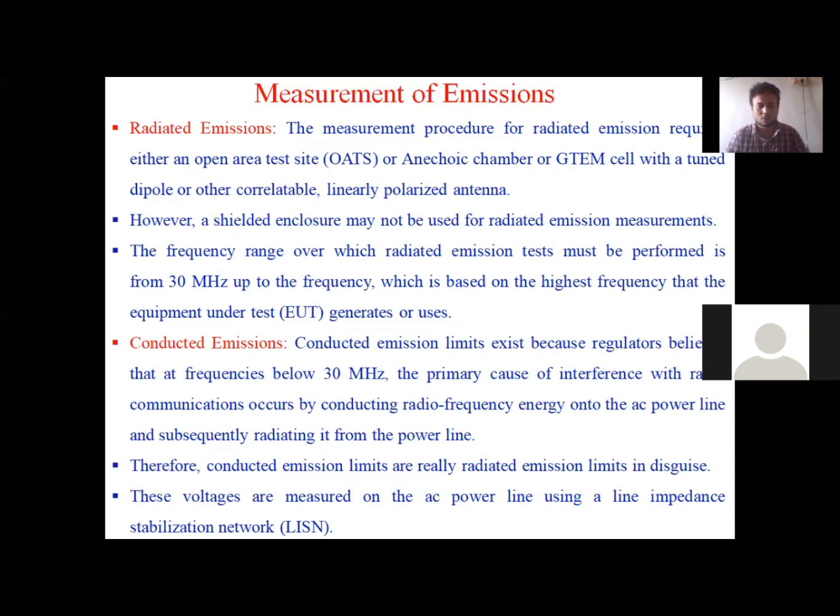Anechoic chamber is a room where the environment inside that room is quite uniform, and microwave absorbers are placed on the walls of those rooms so as to avoid the multipath propagation and to avoid the fading, so that one can measure the performance of the device effectively. Please remember, those testings are very expensive because anechoic chambers cost is in crores.